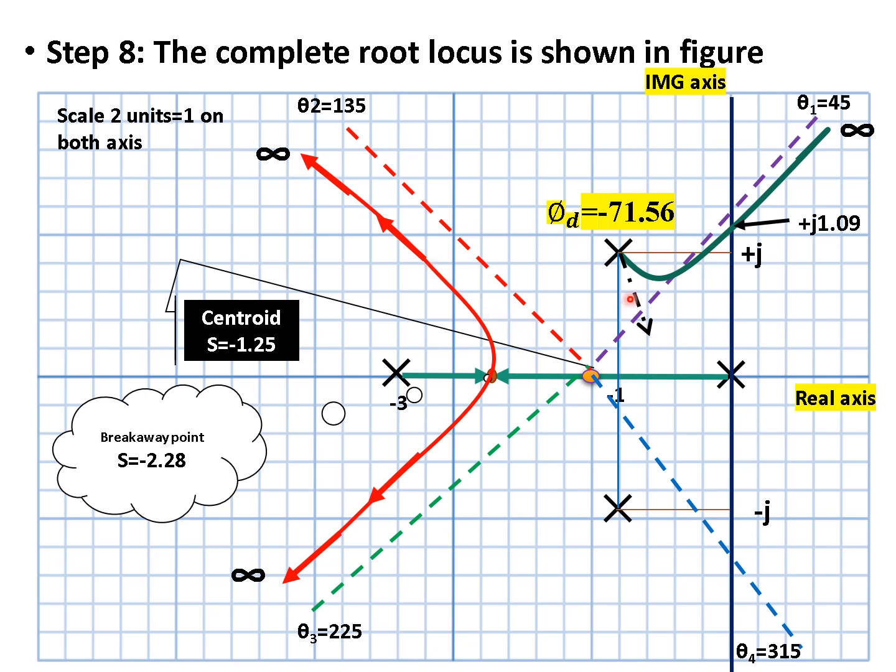First, you need to draw a line horizontally to plus j. After that, from this we need to create an angle that is minus 71.56 in this order, like this. Then we need to draw a curve and it has to move along the asymptotes going towards infinity.